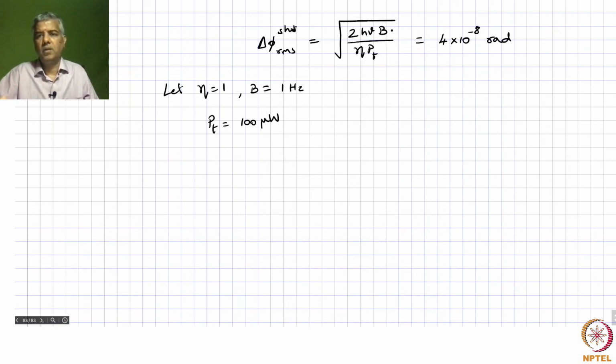There you may incur higher phase noise, but on the other hand, you may not need the kind of resolution in terms of degree per hour that you need for long distance applications. Okay, so that's actually the trade-off.